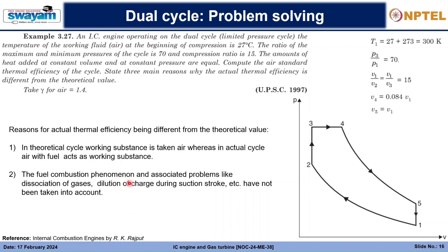So what happens is that in the exhaust stroke, all the gases from the engine cylinder are not removed, and some amount of burnt charge remains, and it gets added up with the new fresh charge. The amount the cylinder can accommodate is the same, but in the same volume some unburned mixture and some burnt mixture is present, and the fresh charge is a little bit less.